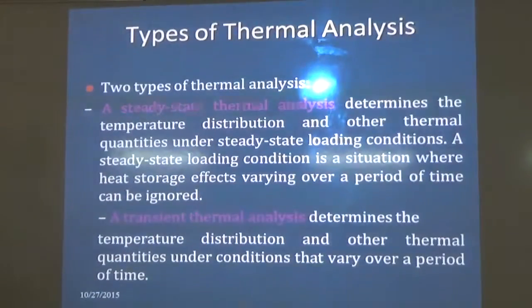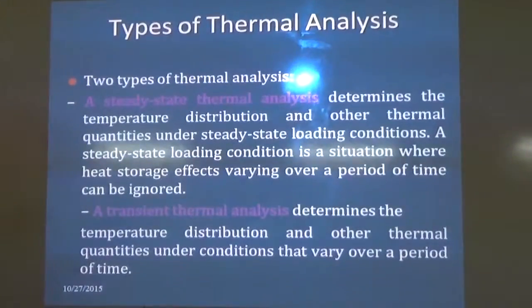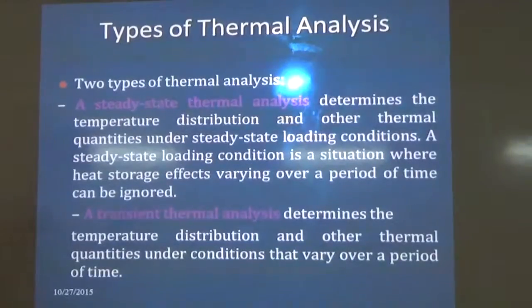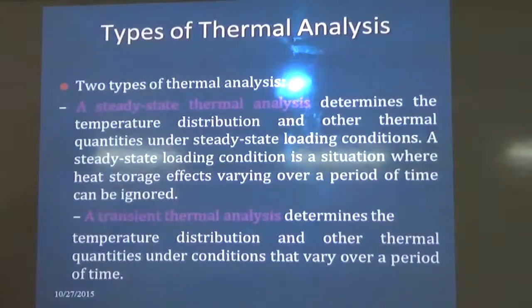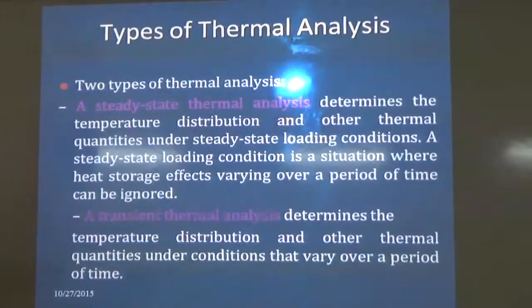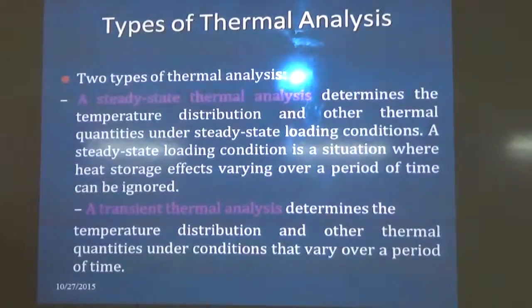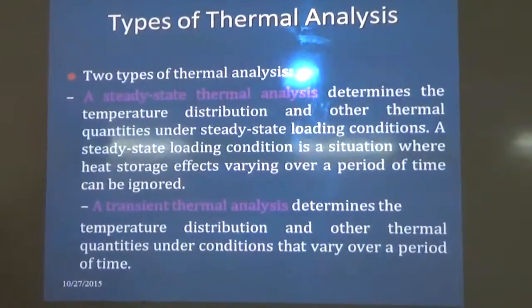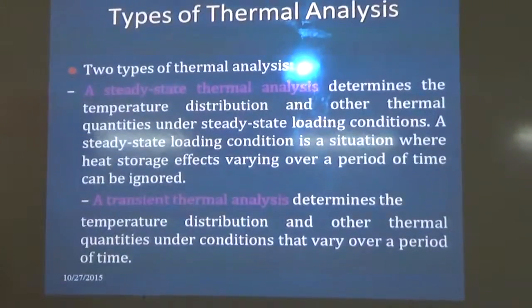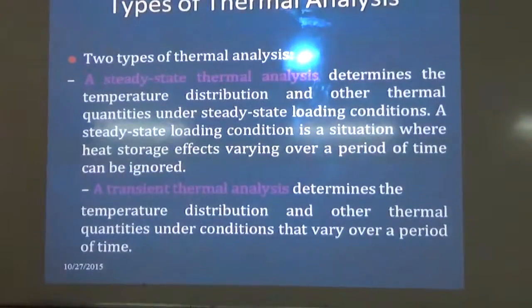Types of thermal analysis: steady state and transient thermal analysis. In steady state, the temperature or the related quantities of interest that we calculate are independent of time. Whether it's morning, afternoon, or evening, the temperature or the heat flux is not going to vary much. If it does not vary much, then you can assume steady state conditions.